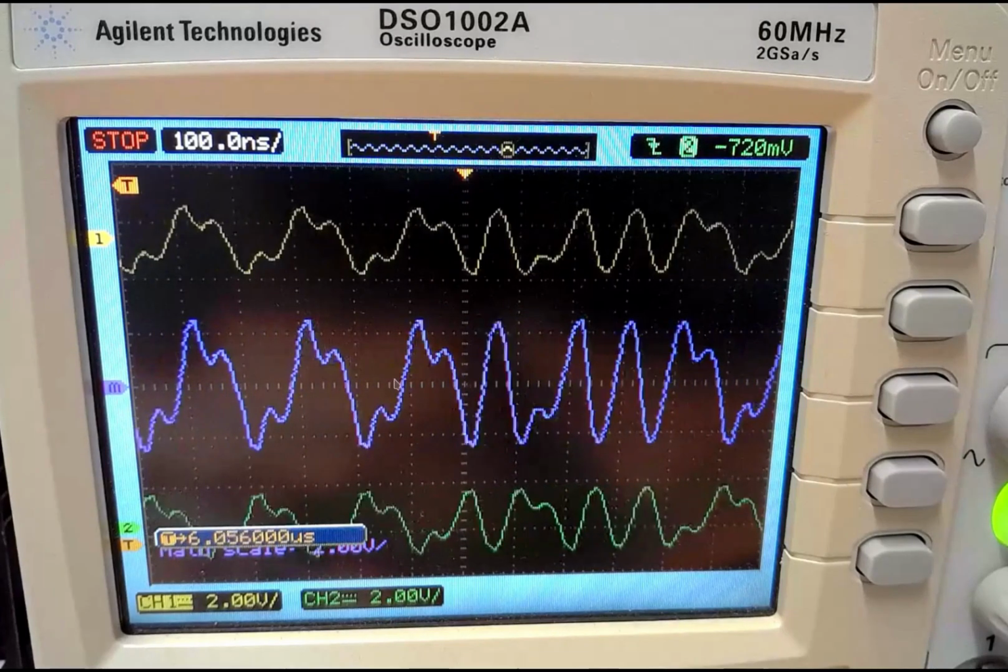Remembering that a 0 to a 1 rising edge indicates a logical 1 and a 1 to a 0 indicates a logical 0. Other key things to note here is that obviously this is a 10 base T system, so we're running at 10 megahertz. We're at 100 nanoseconds per division, so these grid points are your sampling points. So this is when the data is stable. You can ignore the squiggles in the middle, so that is the key point. So the receiving end will be looking at the signal's voltage level at these sample points every 100 nanoseconds.